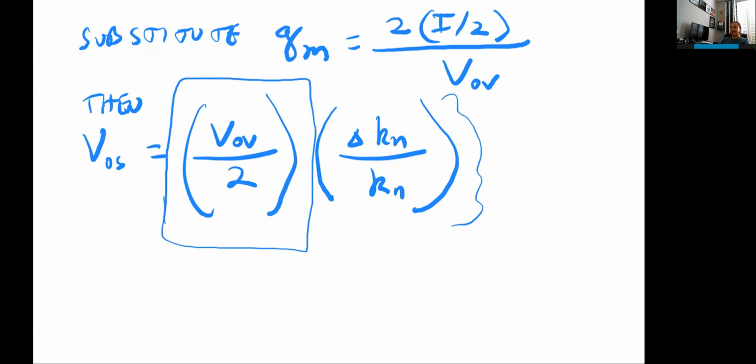So what that says is that every op-amp is going to have some type of offset. You cannot really, on the design alone, get rid of it. Now you can put extra circuitry to actually nullify that offset, and some op-amps have extra ports or extra pins, if you're thinking of a chip, where you can put a resistor across it, like a trim pot, and actually nullify the offset.